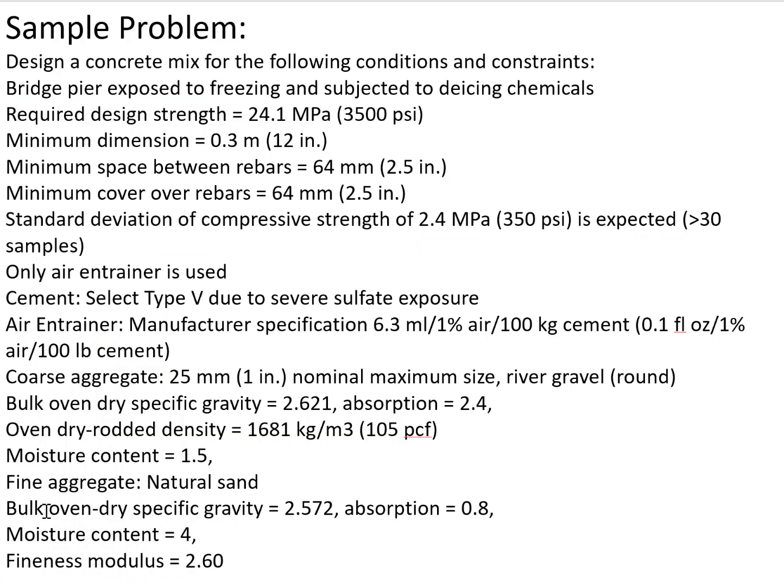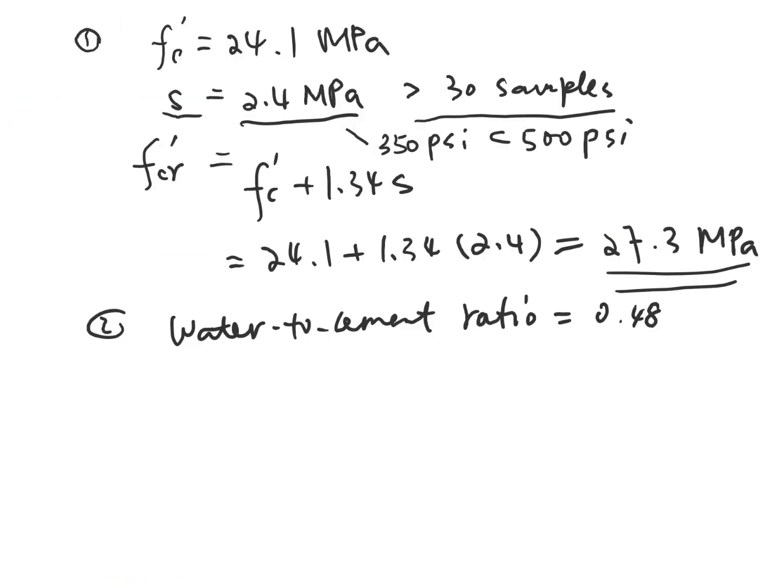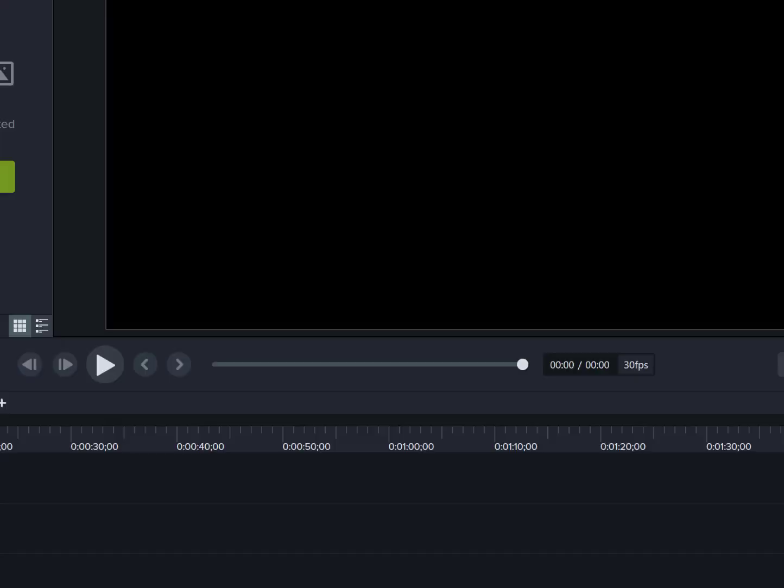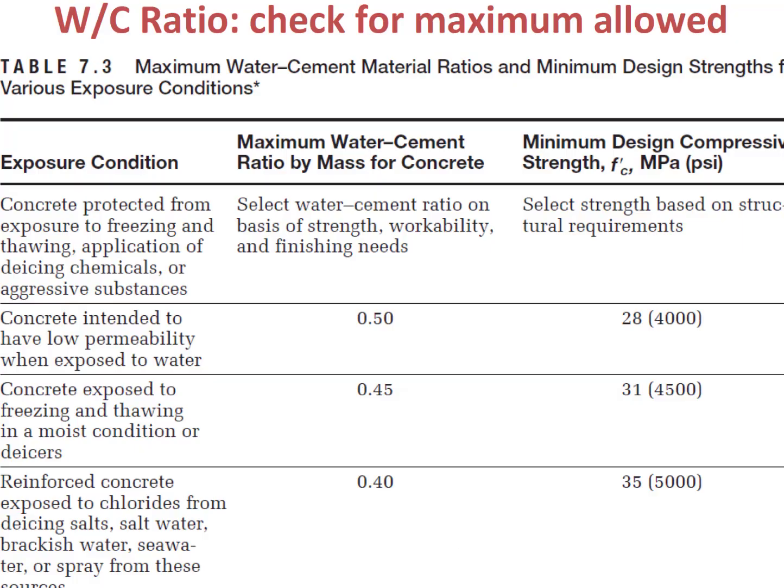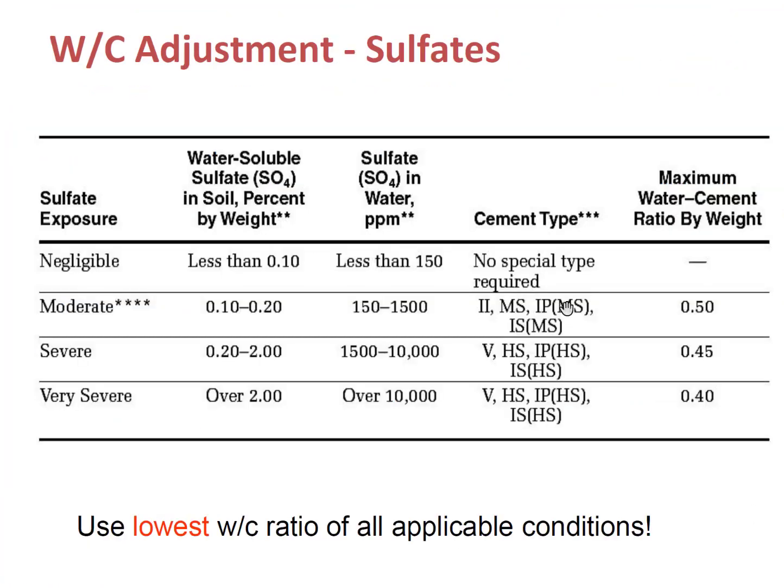0.45. So previously we decided it's 0.48, but it should not exceed 0.45 based on the exposure condition. So we can further check if there is any other exposure condition like sulfate exposure.